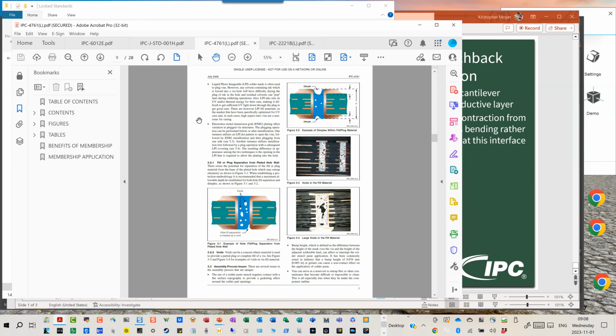And we have a number of different structures. Now, the very first thing to be concerned with, to answer Kevin's first question about the reliability of those via barrels, or my personal opinion on that method: number one, I never use any protection structure that does not fully fill a via barrel.